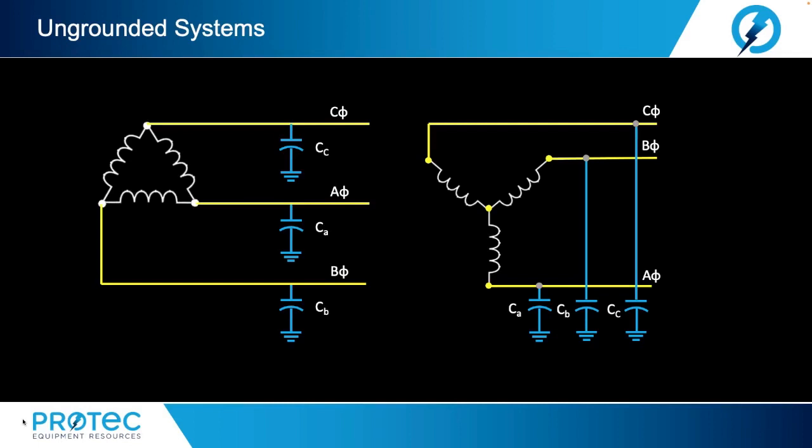The term ungrounded is somewhat of a misnomer because in reality, there is a capacitive coupling to ground of the phase windings and conductors represented in blue on the schematic shown. In normal conditions, this distributed capacitance establishes a neutral reference that permits the phase conductors to be stressed only at line to neutral voltages. During ground fault conditions, the capacitive coupling provides a current path return to the unfaulted phases. This is defined as the charging current of a system.